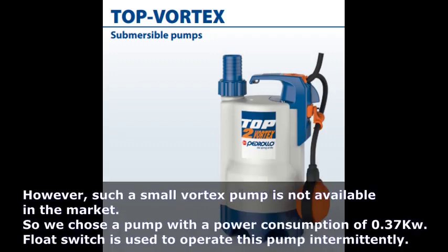However, such a small vortex pump is not available in the market. So we chose a pump with a power consumption of 0.37 kilowatt. A float switch is used to operate this pump intermittently.